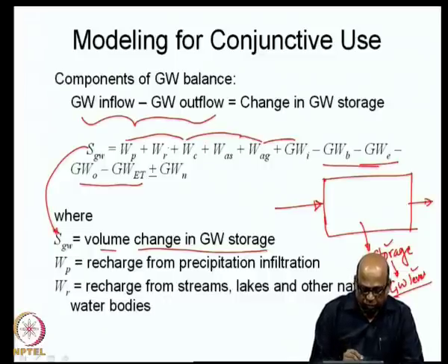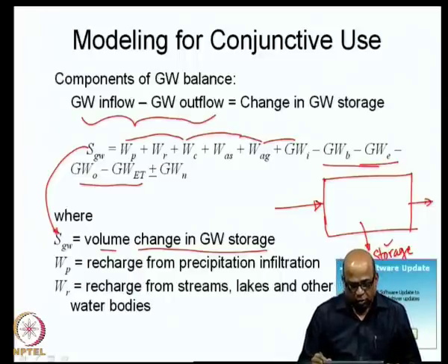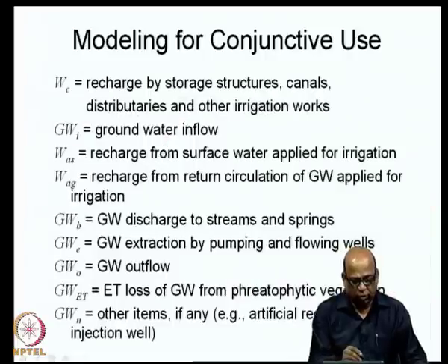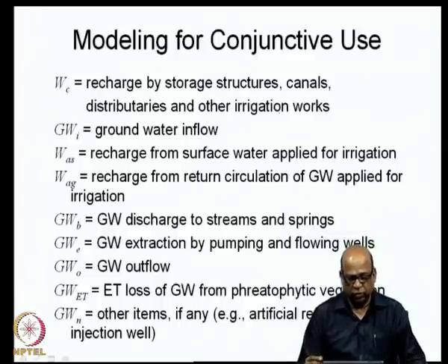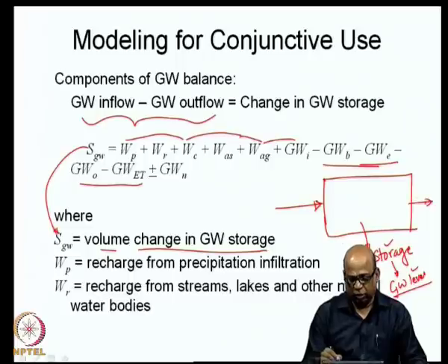Then you may have recharge from streams, lakes and other natural water bodies, that is WR. Then we have recharge by storage structures, canals, distributaries and other irrigation works. This is because of the seepage through the canals and the storage and so on. Then you may have the groundwater inflow. If you are looking at the aquifer boundaries like this,